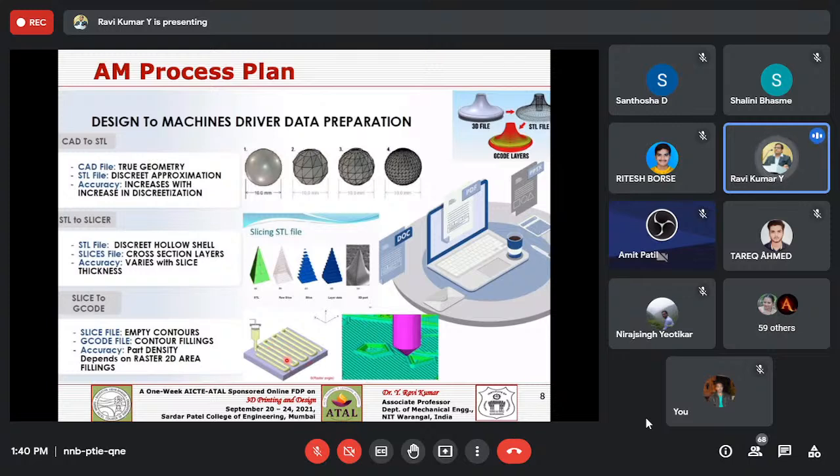You can vary the density or the filling density, depending on your application. Sometimes you intentionally make porous structures, or sometimes 100% dense components. You can have control over your mechanical properties and physical properties, so you can change your tool paths as per your requirement.